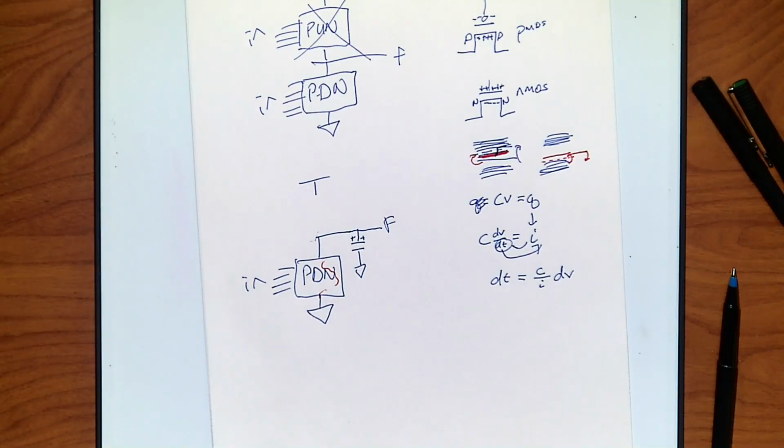So F is on as long as there's nothing discharging that capacitor, right? Because that PDN is going to discharge really quickly. We're making a very big path to ground, so that's going to be your easiest discharge path. And we'll go out into a next network. It's going to go into a gate, which is basically the other side of the capacitor.